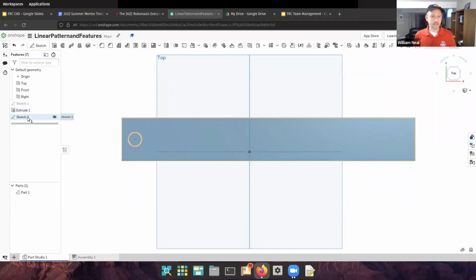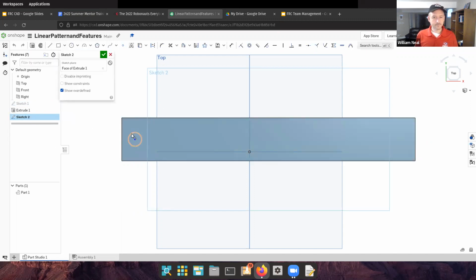And I will take the second sketch and then make an extrusion. So where is this extrusion? We will see here. I may actually have to make that linear pattern in my sketch. Let's just go back here. So I've selected my sketch feature, that's the circle. Let's try to make the linear pattern first before we extrude it. So I've got a circular pattern selected. Let's go back to linear pattern.